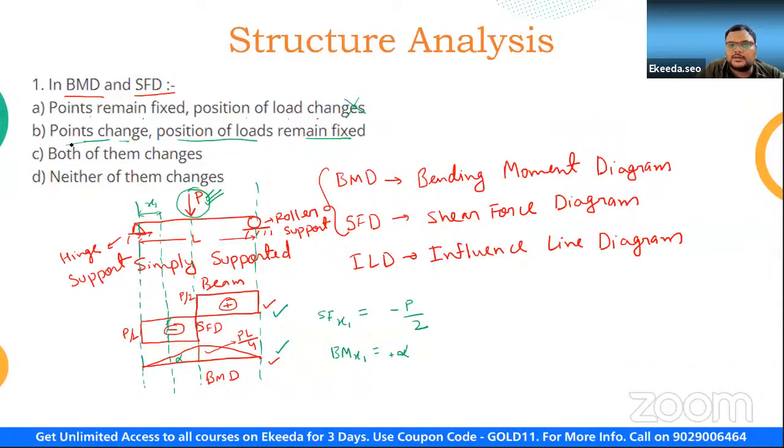So always remember, in the bending moment diagram and the shear force diagram, the difference is that the position of load remains fixed and the point changes. So what will be the correct option for this one? The correct option is option B. Right, guys? In the bending moment diagram and in the shear force diagram, the position of loads remains fixed, but the points change. Now let us see what will happen in ILD, that is, the influence line diagram.